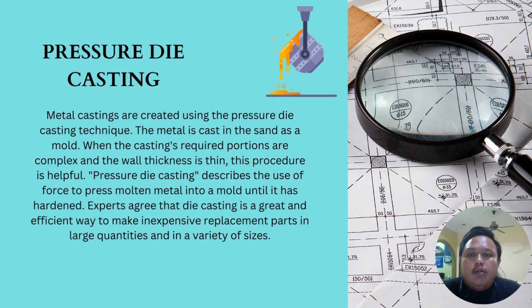Pressure die casting. Metal castings are created using the pressure die casting technique when the casting required portions are complex and the wall thickness is thin. Pressure die casting describes the use of force to press molten metal into a mold until it has hardened.